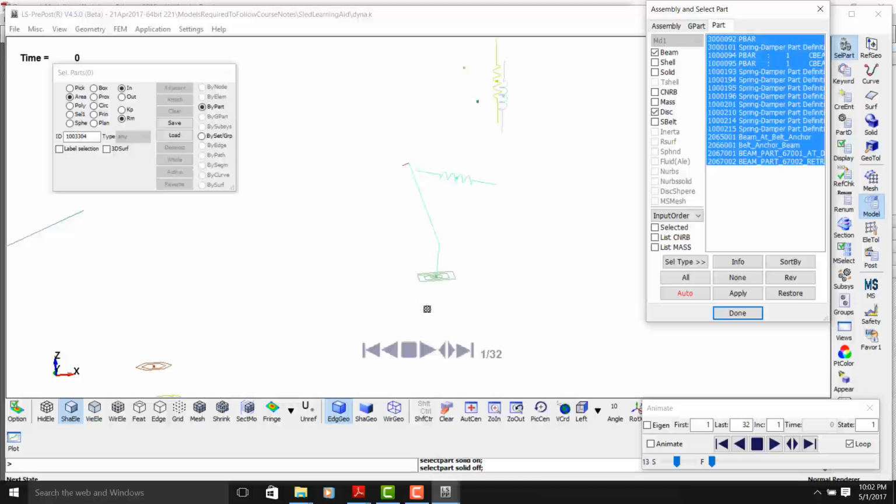is the chest potentiometer. In the real dummy, the same thing is there. And there is a spring here, a rotational spring. If you study the dummy file very carefully, and I'm encouraging you to study the dummy file for all these things, there is a spring here, a rotational spring, of very low force value.